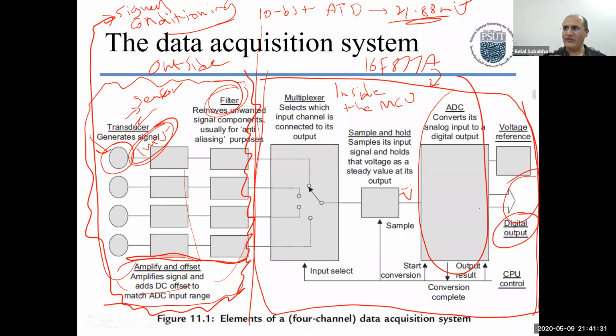If you're reading something like 128, 128, 128 from the sensor, but then suddenly you get a 200 spike, then averaging, for example every 5 readings you average them, is a type of low pass filter, right? You get rid of these kinds of spikes. Anyways, then here comes our pins.